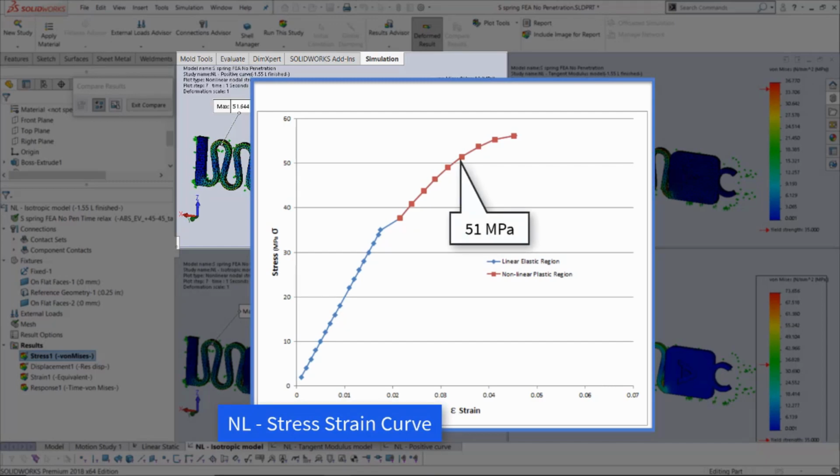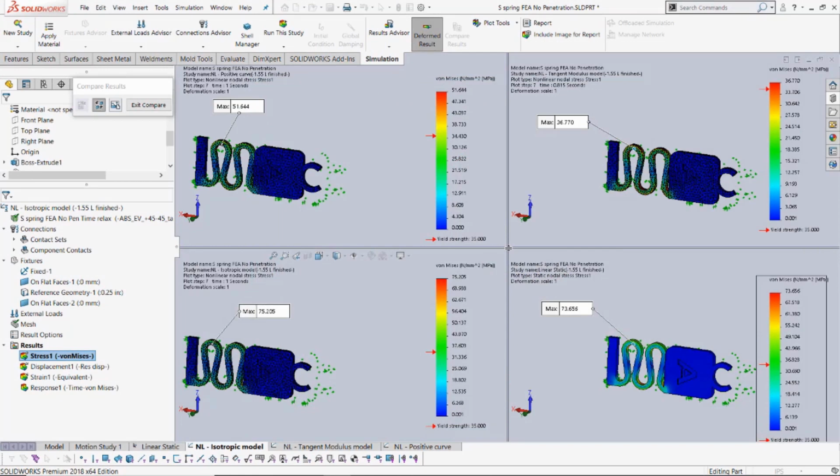These are going to be the most accurate stresses. Now, to achieve a much more accurate stress, here you might want to consider using the true stress of the material or the engineering stress. All you have to do now is increase the mesh until the stresses don't change significantly.